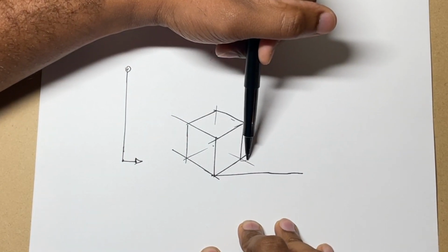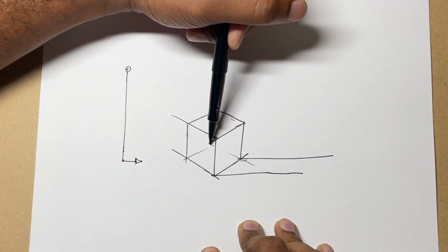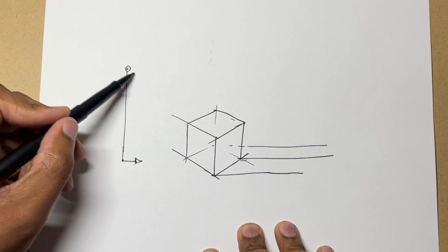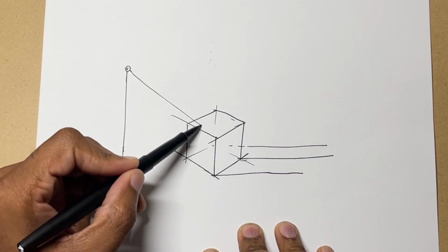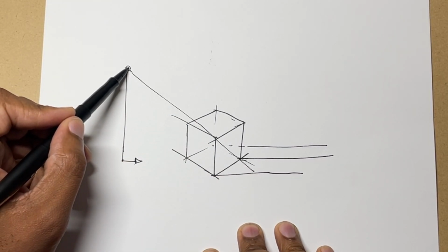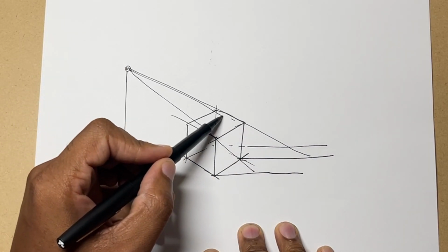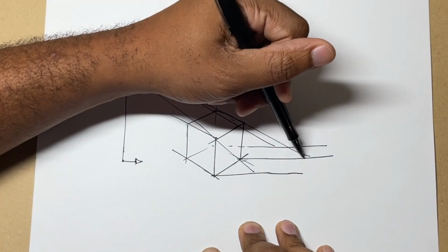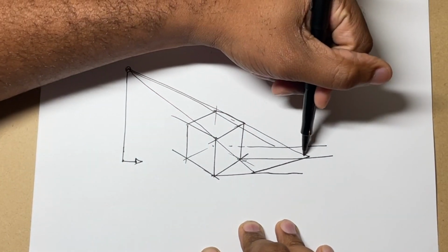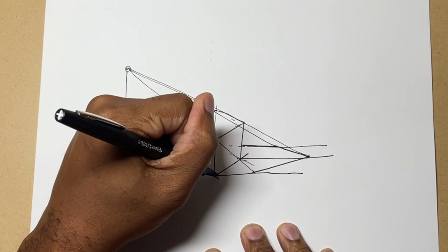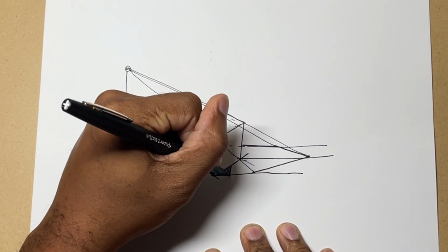I'm going to draw a line from the 3 points on this ground plane that will be in shadow. Then I'm going to draw my angle line from the light source through the corresponding points on the top plane of the cube. And then I connect those points, right? Remember, these are the intersection points or the shadow edge.